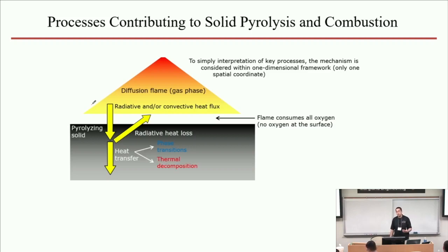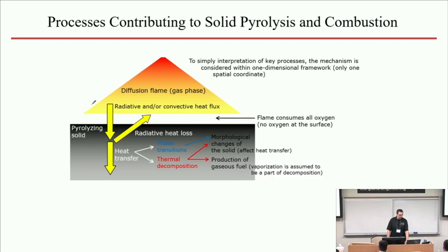Those are the chemical reactions that ultimately are responsible for production of gases, some of which become fuel for your surface flame. Now, all of these processes also set off morphological changes inside the materials, which include charring, which is something you are very familiar with if you have ever seen how wood burns, formation of various cracks and fissures in structures, formation of bubbles, and also potentially a melt flow that is associated with the materials that are usually thermoplastics.